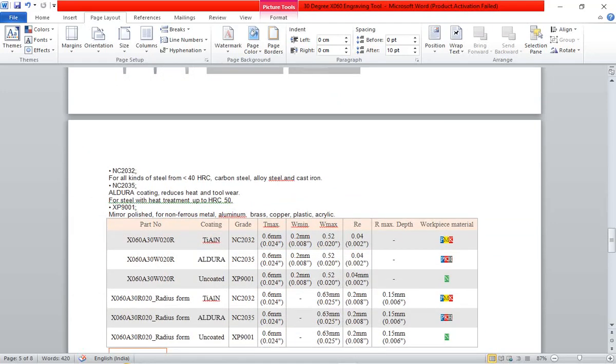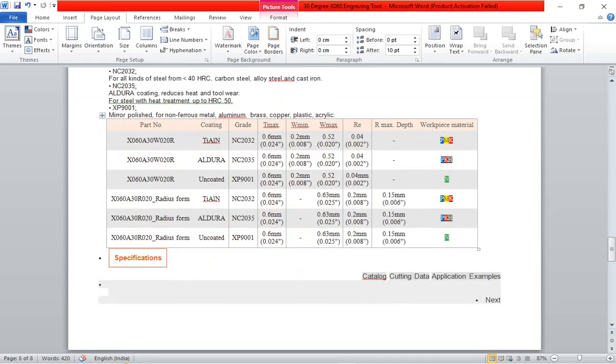So the depth should not exceed 0.6 in your workpiece. It should be less than 0.5 or 0.6. If we put 2 mm or 3 mm, the cutter will be broken and we will not do any engraving. These are the standards. You have to read and take careful note of this nomenclature before using engraving tool.